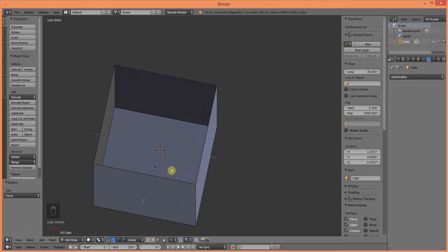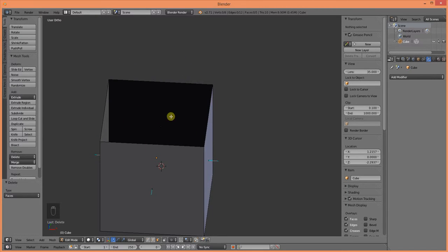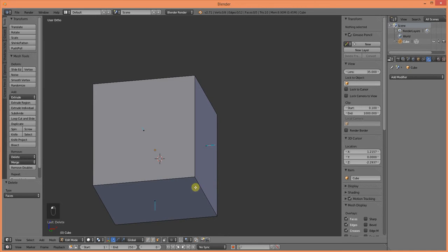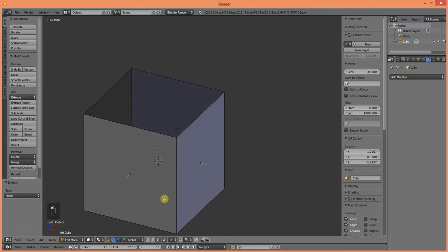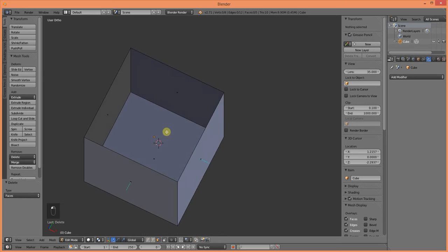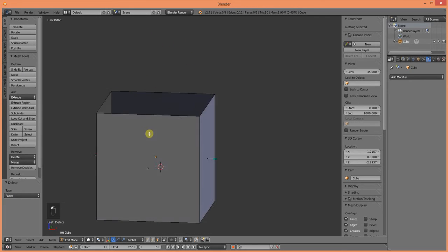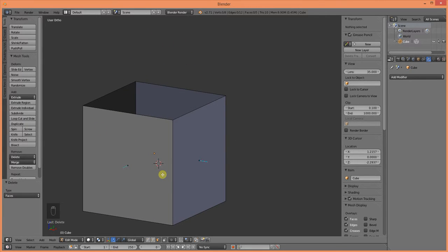I have experience in trying to print with an open face like that. Usually if it's on the bottom that you have an open face, then it's just going to go ahead and fill that in. I'm not real sure about the top. Your slicing software is actually doing a collision detection, so it's checking all points on each layer to find out where it's colliding with until it gets to nothing up here. So you could end up printing a solid box, you could be printing absolutely nothing.